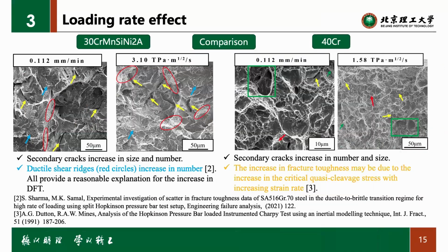And to deeply understand the loading rate effect, I did some comparisons for different materials. For 13CR, it can be seen from the left picture that the secondary crack increased in size and number with the increasing loading rate.